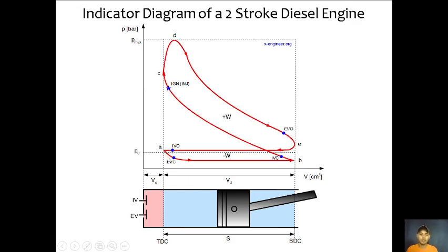So at this point, the exhaust valve closes in here, so the valve overlap stops, and then purely intake is activated, and then the intake valve closes, and then back to compression, power, exhaust. So that's how a 4-stroke diesel engine works.